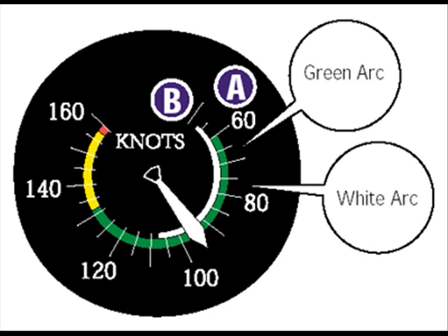The airplane can descend faster at cruise speed with reduced power while getting you to your destination sooner. Since flaps provide more lift at slower speeds, think carefully about how and when they are retracted when airborne. If you're making a full flap approach and it's necessary to go around, that is, give up this approach, climb, and return for another landing attempt, don't retract the flaps all at once. This would be like having someone remove a part of your wing at a slow speed.